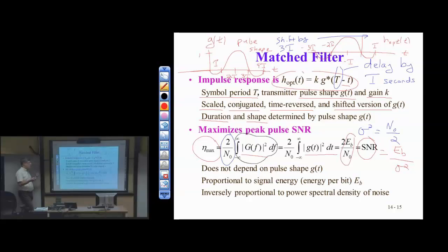So it just depends on what system you want to simulate as to what SNR values are relevant to your simulation. In simulation, what we're going to do is keep the signal power constant and change the variance of the noise that we synthesize in the channel. That allows us to test the system over different SNR points. If I know what the energy per bit is, and I know what the variance is, it tells me what the SNR is here, and this is in linear units, not in dB. We have to convert to dB.